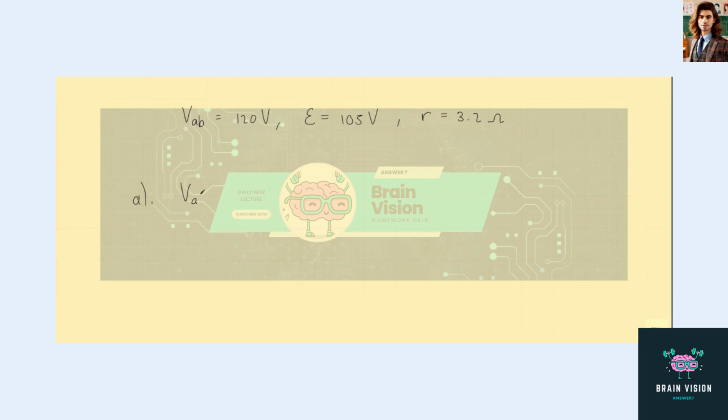So the potential difference VAB is equal to the EMF epsilon plus the potential difference across this internal resistance, I little r, which means we can rearrange this equation and solve for the current. And we get the current I is equal to VAB minus epsilon over the internal resistance r.